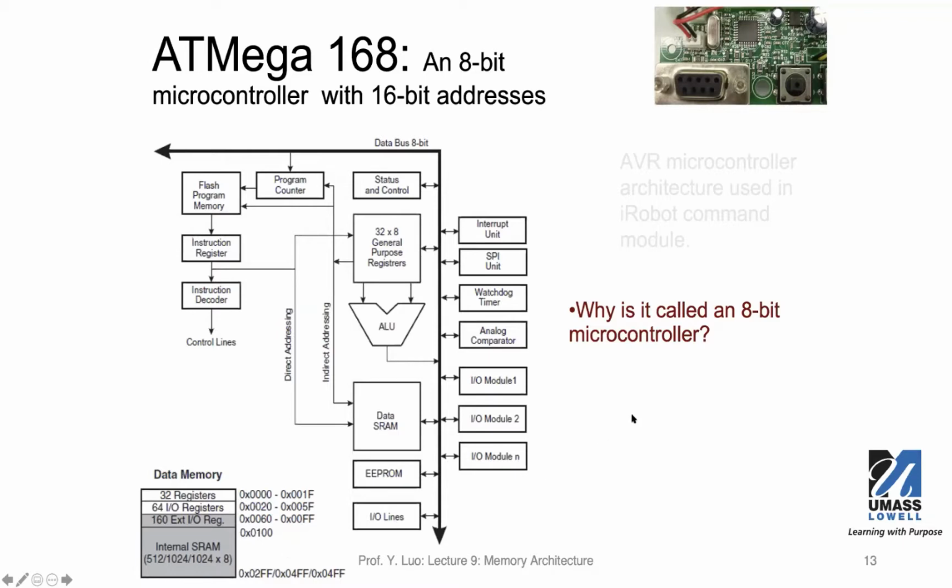So the question, why is it called an 8-bit microcontroller? It is mainly because the ALU takes 8-bit values from the general purpose registers, and all the general purpose registers are 8-bit wide, and also the computation, the data bus is 8-bit.